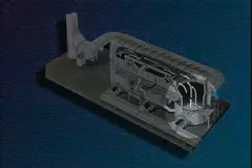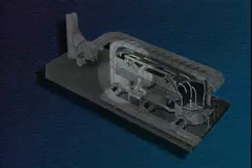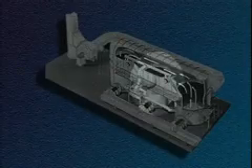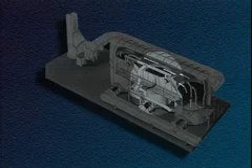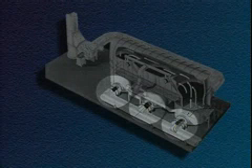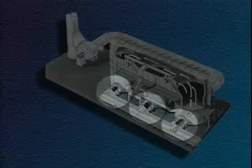One bed is used to preheat the waste gas stream. One bed is used to store heat from the treated gas stream. And one bed is in a purge cycle. The purge cycle is needed to prevent emission spikes each time the gas flow is reversed. A set of gas flow dampers is used to switch the inlet, outlet, and purge gas streams to the appropriate beds.